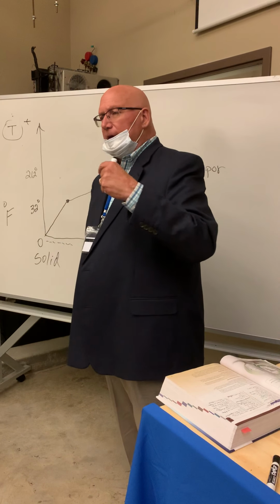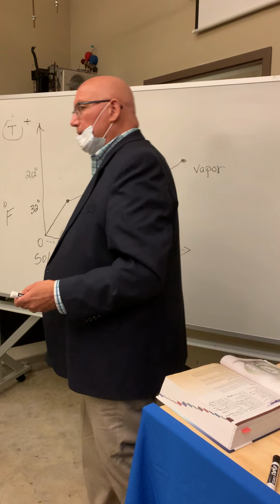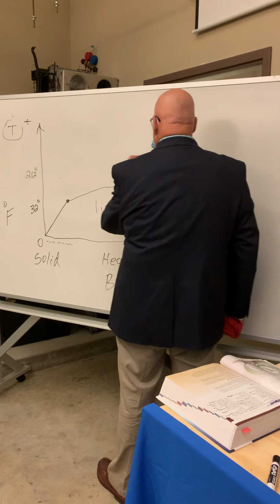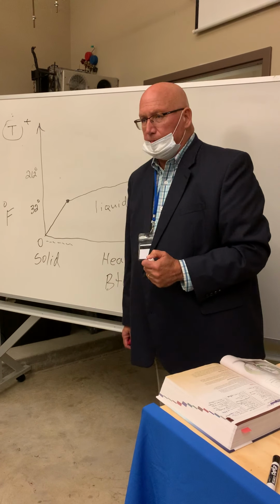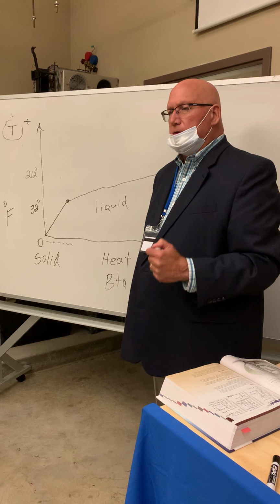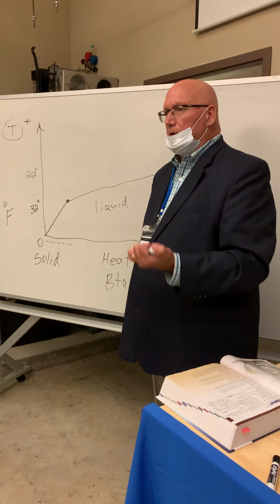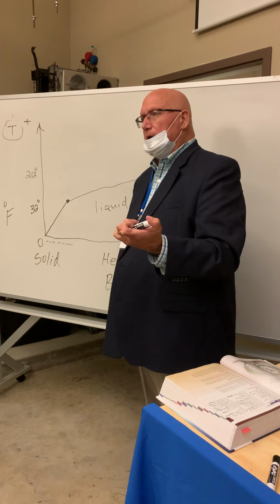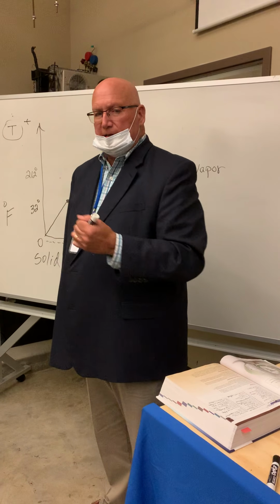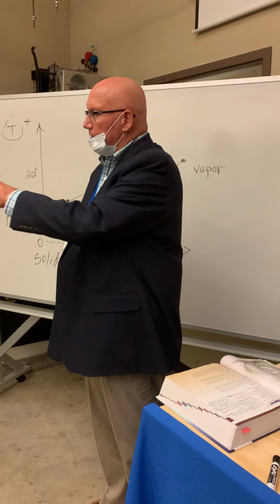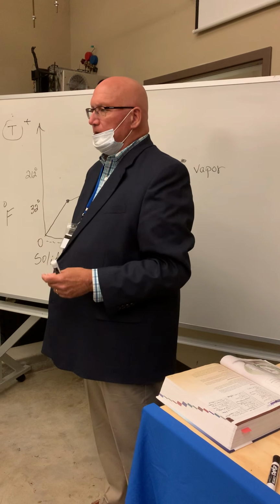So if that's how we get something to boil off, then if we go in this direction by removing heat, we get the reverse to happen. And that's what we do in air conditioning. We take our refrigerant, we absorb the heat in this room, and then we take it to a condensing unit. These things you see right here, and we release that heat to the outside.